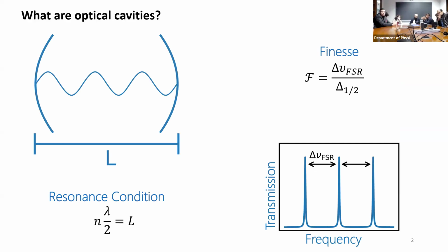So if I want to use for 550 and then for 750, it means I have to change the reflectivity or change the cavity. In the fibers, you cannot change the length or the reflectivity. So you need different fiber cavities for them, one to work with one and another to work with another. If the wavelengths are integer multiples of each other, then you can use them at the same time. But otherwise, yes, you need different lengths for them.